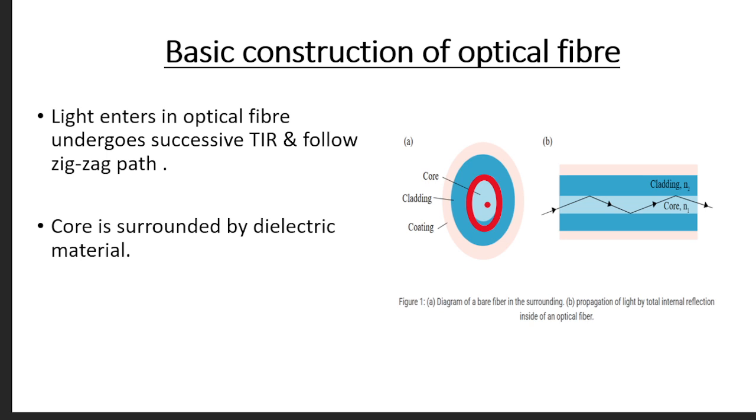So what is the use of cladding here? Cladding is added to reduce the scattering losses at the core surface and to enhance the strength of the fiber. It is also used to protect the core from absorbing surface contaminants with which it can come in contact. Most fibers are encapsulated in a plastic material called buffer coating, sheath or jacket, to add further strength.